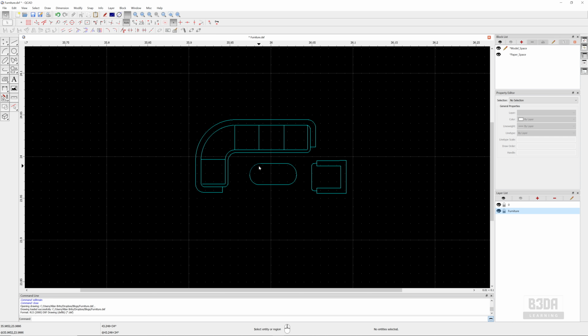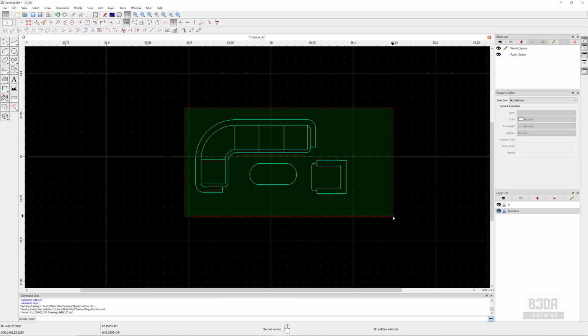If you are not used to CAD tools, a block is like an asset of a CAD software, and you can make copies, and each one of the instances has a link to the block, and if you edit the block, all of the instances will receive the updates. They are connected. We can try to do the same thing here with this sofa drawing.